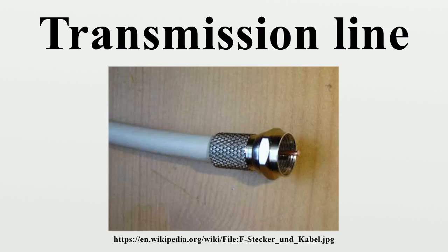The higher the frequency of electromagnetic waves moving through a given cable or medium, the shorter the wavelength of the waves. Transmission lines become necessary when the length of the cable is longer than a significant fraction of the transmitted frequency's wavelength. At microwave frequencies and above, power losses in transmission lines become excessive, and waveguides are used instead, which function as pipes to confine and guide the electromagnetic waves. Some sources define waveguides as a type of transmission line, however, this article will not include them.